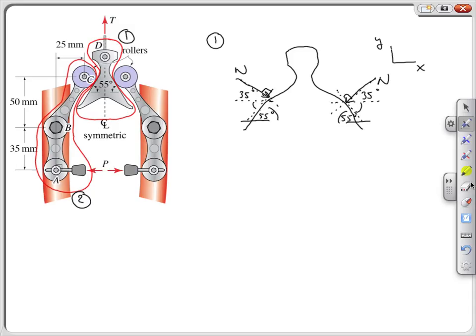The symmetry of this arrangement means that the forces that we have acting on this body are concurrent. If I've drawn them correctly, they should all intersect in the middle here, which means we have a concurrent force system, and the cam is automatically in moment equilibrium or in rotational equilibrium.